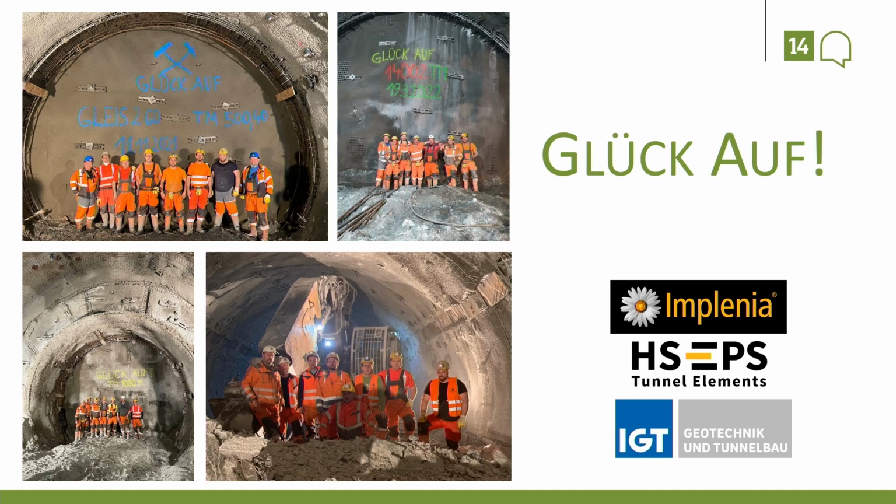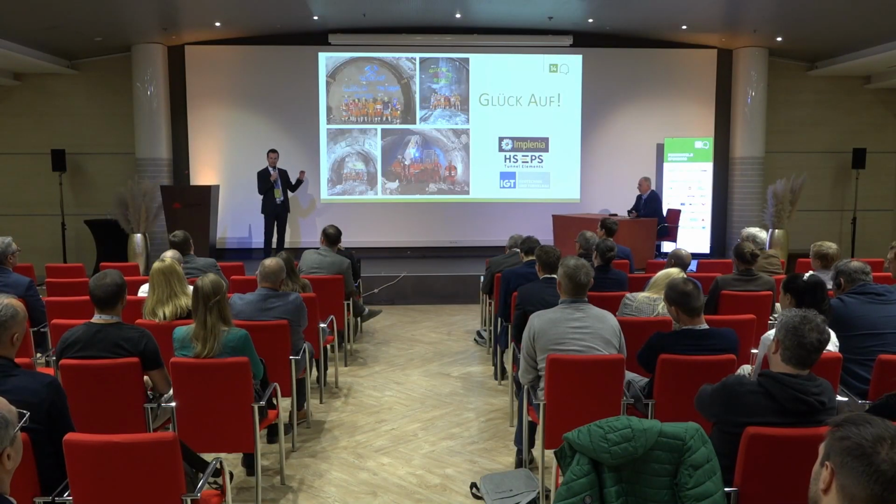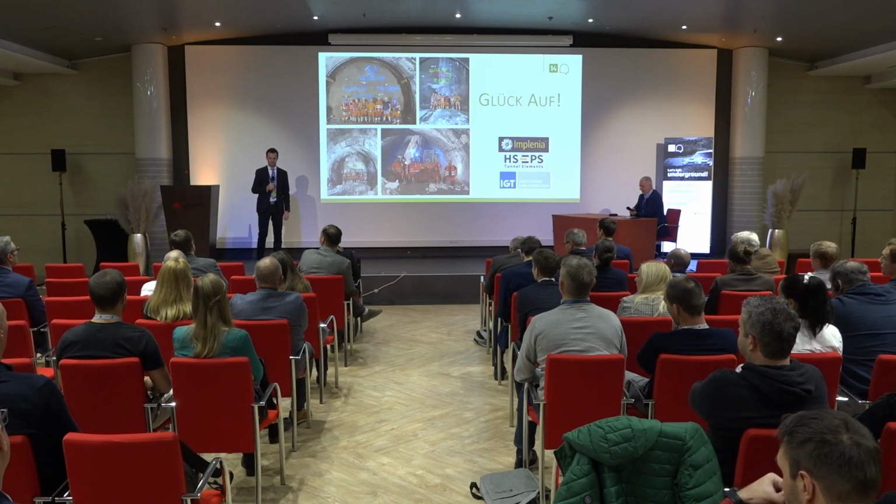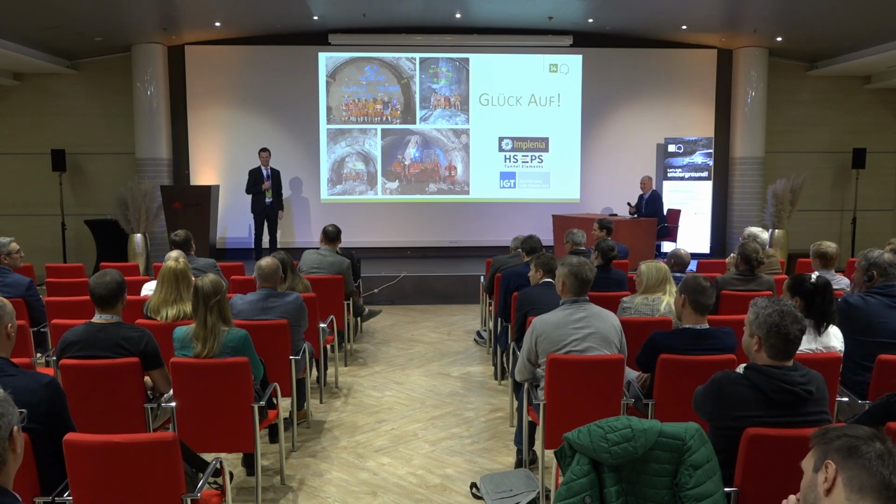But the lattice girder is not a really stiff support element in this type. Compared to the yielding elements, it's really soft. If you have large deformations, at the first few centimeters, of course, you have some resistance of the lattice girder, but then they immediately start to buckle at the position of the yielding elements, and then the resistance is relatively low, so it's also a ductile system. Thank you. Still a lot of steel gets put in, but thanks for the explanation.